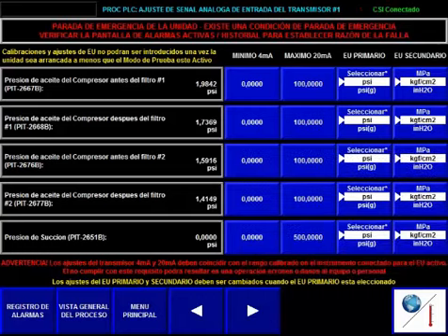You can see selections for primary and secondary units. These may be changed. Currently, pressure is set up for PSI on primary, and kilogram force on secondary. By touching the button, it'll present a selection if you want to change to a different secondary range, secondary engineering unit, I'm sorry.